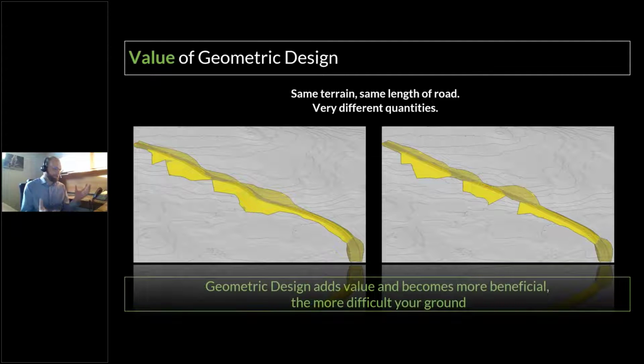And you may say, well, I can just look at that and know that if I contour around the slope, it's going to take less material. It's a benign example, but just imagine if it was more pronounced. It's a question of, well, can I actually get around that slope and keep my design standards as I like? Is it going to be safe to drive on? If I go from having that through cut on the straight road to daylighting it out to minimize some of my cut, is that cut slope going to extend down somewhere where it shouldn't be? So it's all about giving you a better picture of what's going on and an idea of what you're up against and planning around those challenges as you encounter them.